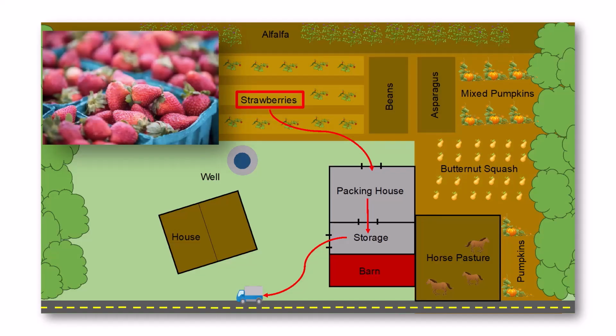To create the sketch of your farm, first obtain an aerial map or maps. You can use sources such as Google Earth, Natural Resources Conservation Service, the Farm Service Agency, or County GIS maps to get started. Once you have a map printed, sketch out the location of fields, irrigation sources, and water lines, and buildings such as packing houses, chemical storage, or produce storage.